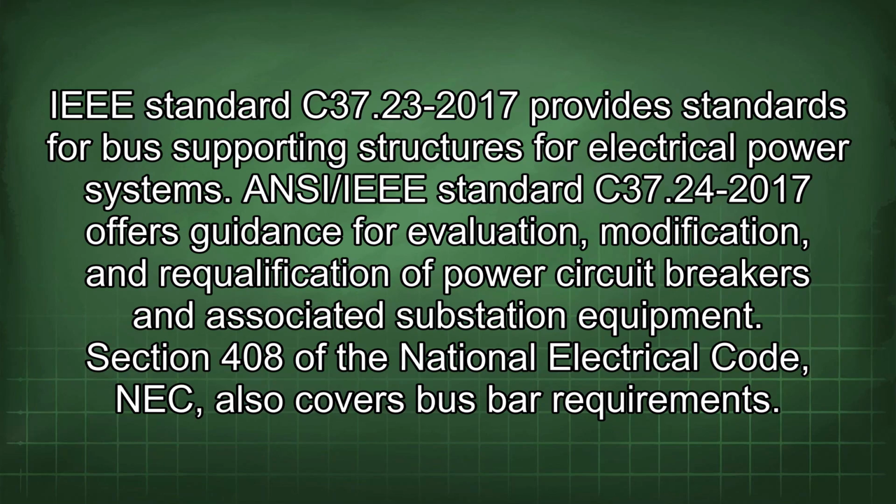IEEE Standard C37.23-2017 provides standards for bus supporting structures for electrical power systems. ANSI/IEEE Standard C37.24-2017 offers guidance for evaluation, modification, and requalification of power circuit breakers and associated substation equipment. Section 408 of the National Electrical Code, NEC, also covers bus bar requirements.